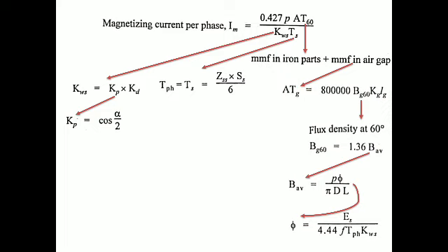To determine the alpha, just refer the book. That alpha value is in degrees. You have to substitute here in degrees, but the data is given as a coil span of 11. So with this, you have some data here. Slot per pole value, which you have to multiply by 180 degree. Then you can find the value of alpha is nothing but 15 degree. Just check the book. Then after that find the K_p.